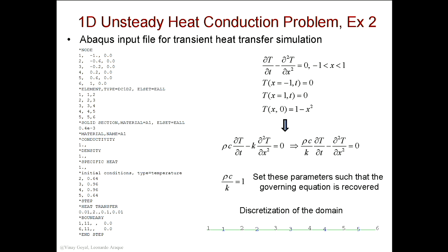Are you tracking? I don't know if you follow me. Some of you may not have noticed this, but I can actually use Abaqus to solve something that has nothing to do with heat transfer. I can select another problem, and maybe rho c and k for my other problem have nothing to do with heat transfer, but you can specify what rho c and k are, so it becomes the problem that you're interested in. Do you follow? Okay, so I'm teaching you this because I've done something similar. I've tricked Abaqus to solve a non-heat transfer problem. Okay, there's a question right here.